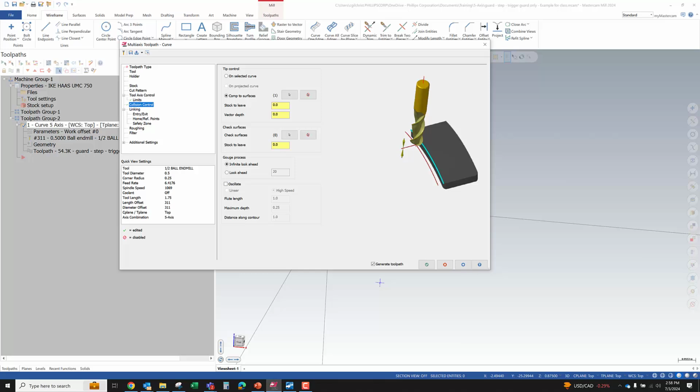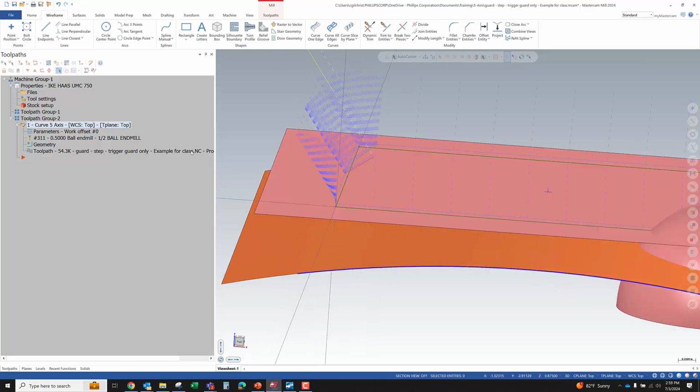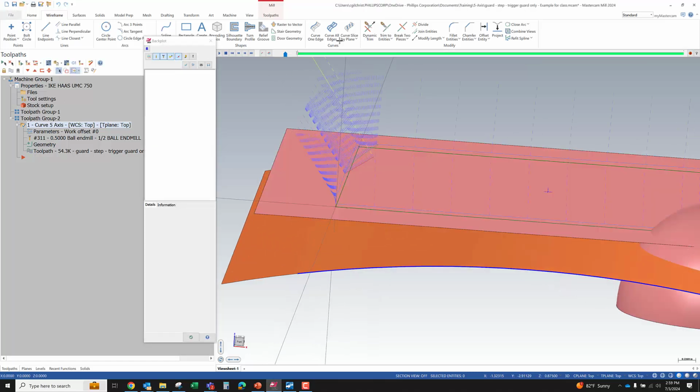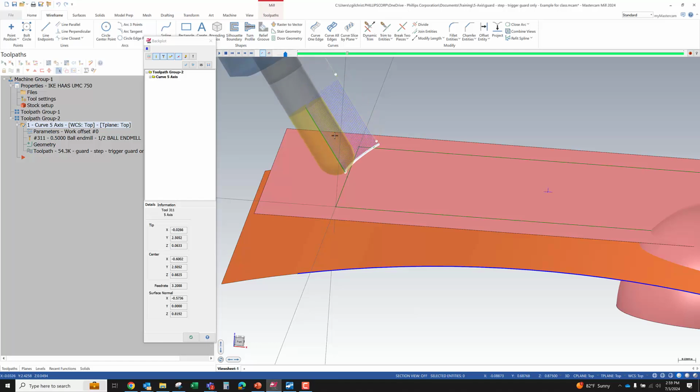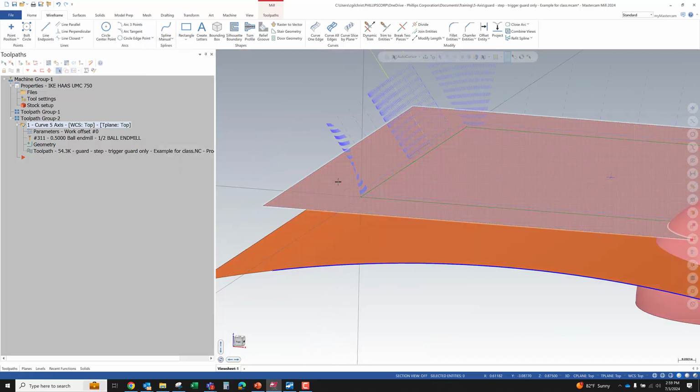So for example, projection, right? Following stuff where the surface and the edge that you're following is right on the edge of the model. If it was just in 3-axis, that would work great. But like we saw with this, as soon as we start adding that tilt to it, now the compensation point, the tangency point of the tool, if I didn't have anything here, here's a great example.